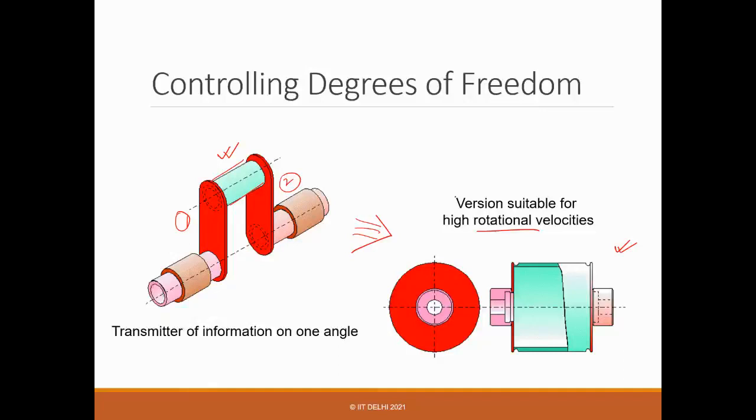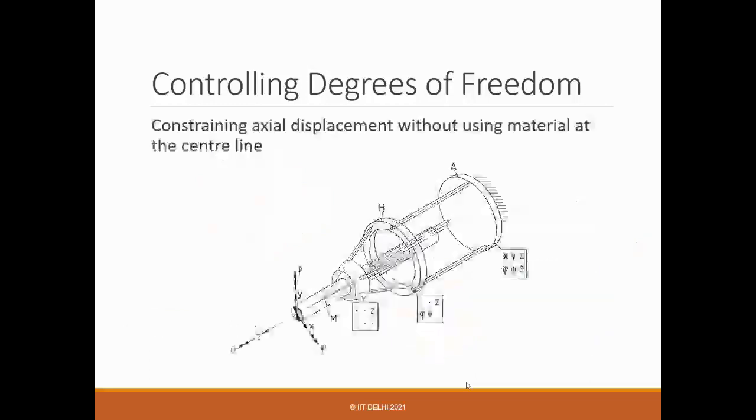So you can see how conveniently it can be designed, and you can see the notches here. These are also providing the necessary compliance, right? But the tube is rotationally stiff. So the diaphragm will provide a kind of U motion, so the two rotations and the two rotations at the other end. So you will get a very good design out of the tube and the two diaphragms. Let's stop here, and we'll continue to discuss this.